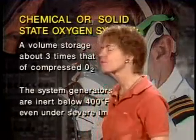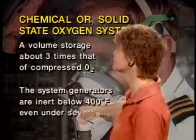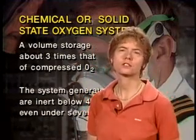So the characteristics of a chemical or solid-state oxygen system are that you have a lot of storage capacity. You have a volume storage capacity of about 3 times that of compressed oxygen. That's one of the advantages of that solid-state oxygen system as a backup.